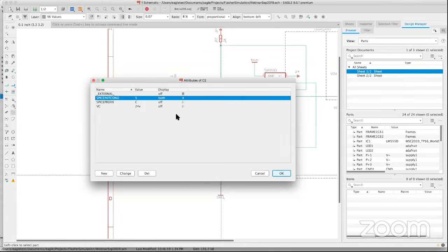If you need to force straight lines, you're better off doing manual routing, to be honest with you. But we actually have another tool, and I don't know if you tried it. It's called Quick Route, and it does a really good job at going straight, to be honest with you. But those are topics I'll cover on Thursday with Jorge.